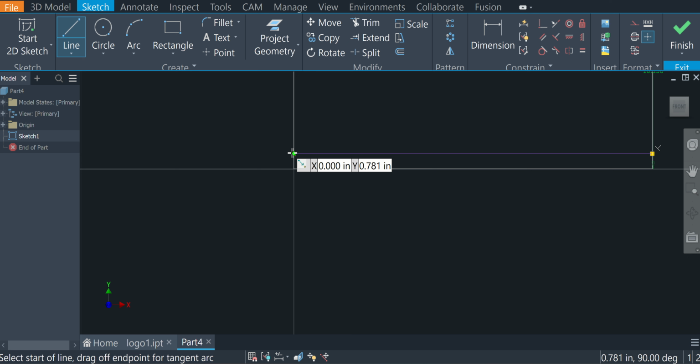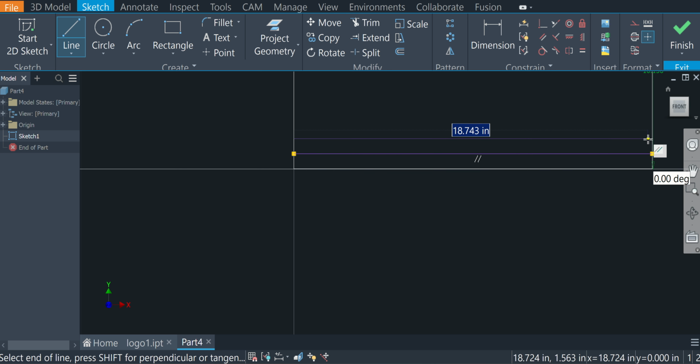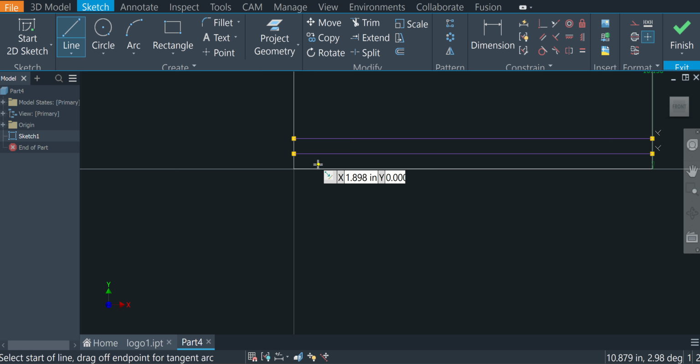And then I happen to know what 25 divided by 32 is, so it's 0.78125. So what I can do is go right here, tab, and then enter 0.78125, and I can times that by 2 for the second line, and I can snap it. I can continue this process. So I can also do tab, 0.78125 times 3.